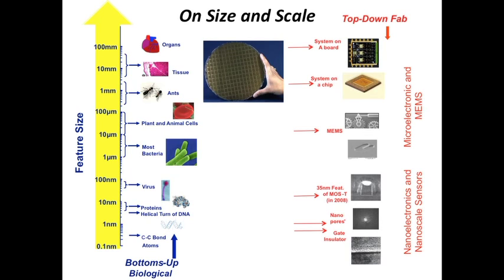So in that case, if we put DNA on one side, which is the negative electrode, and apply voltage, DNA will try to go towards the positive side, right? Based on the potential. When it goes to the positive side, it has to pass through the pore. Once it has passed through the pore, if it is a micron scale, will you see any fluctuation in the current which you are getting? No. Because the pore size is very big and the DNA is very, very small, it will not physically block the pore.